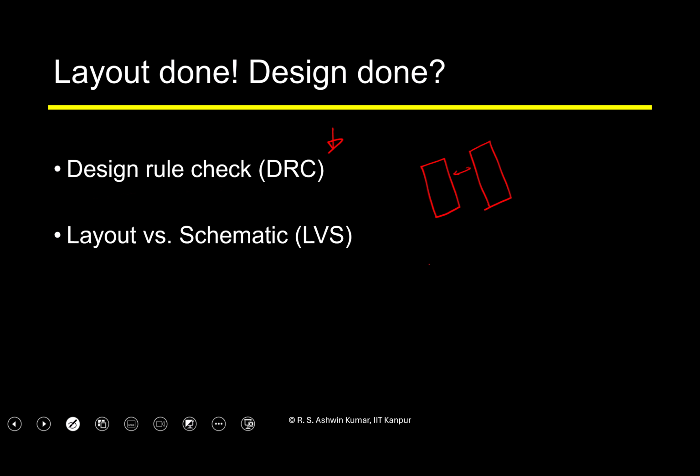The second main thing is to check whether what you have laid out matches what you have designed in the schematic. That is called layout versus schematic. That is basically looking at the two and finding the differences between them. And if there are differences, you go and correct them. Right? That's all.